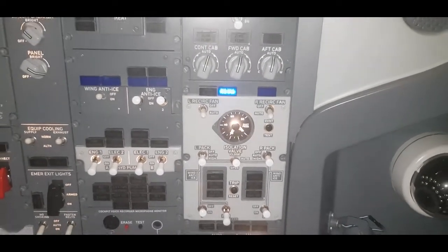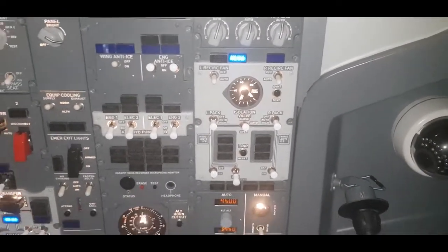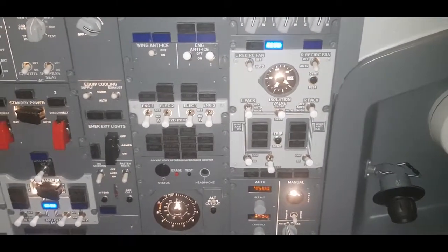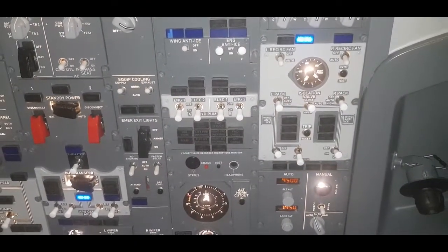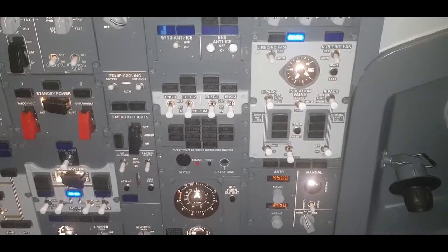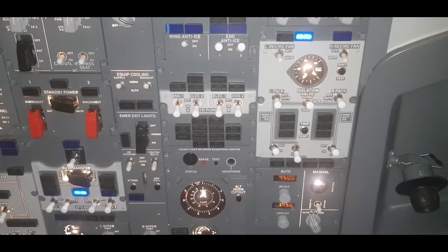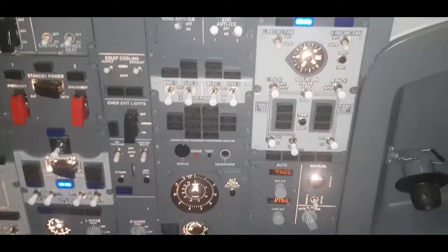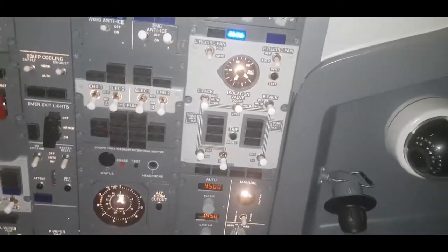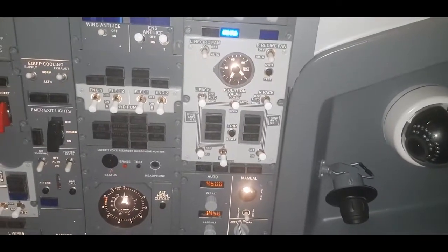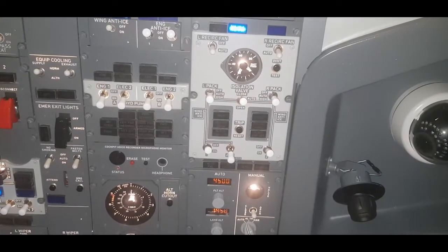Now, after takeoff, we need to make sure that if an engine failure occurs, we cannot position the engine bleed air switch to on until reaching 1,500 feet or until obstacle clearance height has been obtained. And now we will complete what we call the reverse C pattern flow.